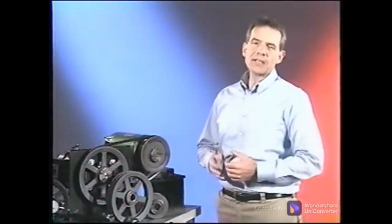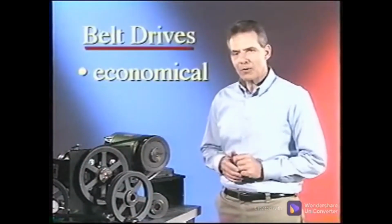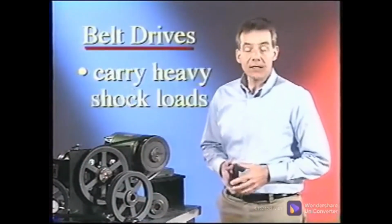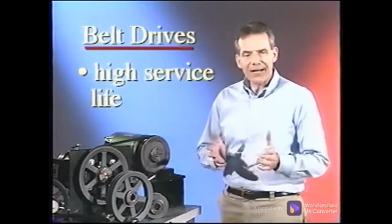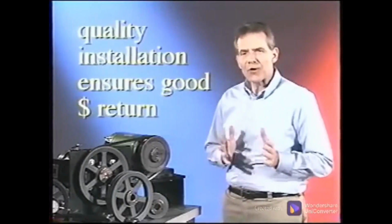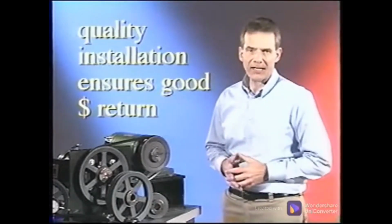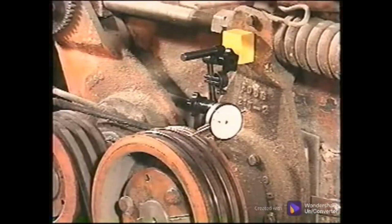Belt drives are normally considered to be the real shakers in the industry, but they're very economical, are fairly easy to maintain, can carry heavy shock loads, have a high operating speed range, and a high service life. When time is invested on the front end to ensure a correct installation, the return on the dollar invested can be a hefty payback. Inspect the sheaves for wear using a groove gauge. Check them for proper alignment and runout, including eccentricity and wobble.